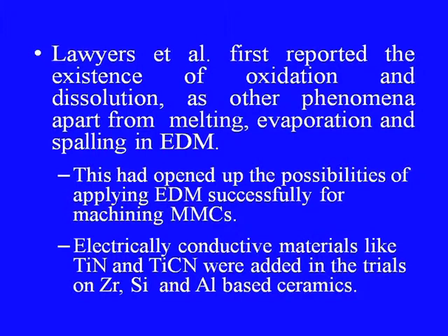Electrically conductive materials like TiN, titanium nitride, and TiCN were added in the trials on zirconium, silicon and aluminum based ceramics. These are some of the attempts on machining of MMCs using EDM.